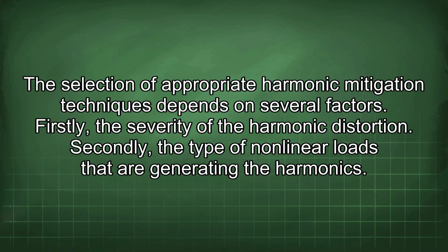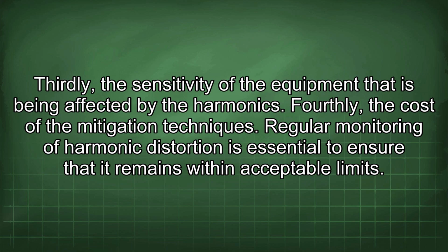The selection of appropriate harmonic mitigation techniques depends on several factors. Firstly, the severity of the harmonic distortion. Secondly, the type of nonlinear loads that are generating the harmonics. Thirdly, the sensitivity of the equipment that is being affected by the harmonics. Fourthly, the cost of the mitigation techniques.